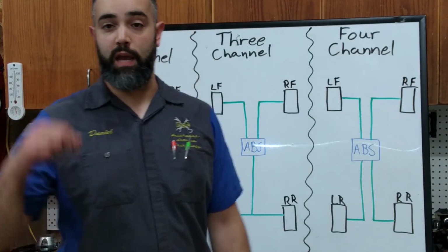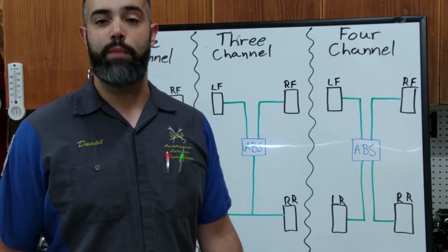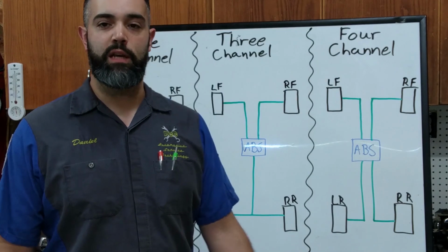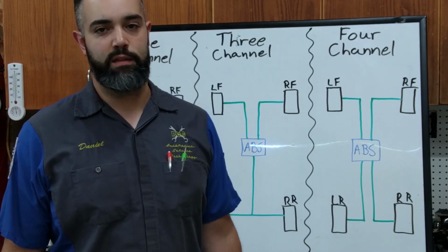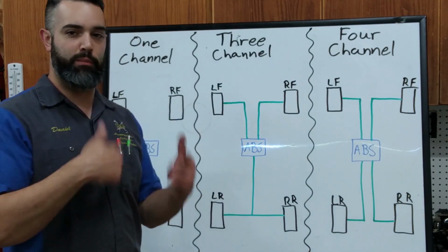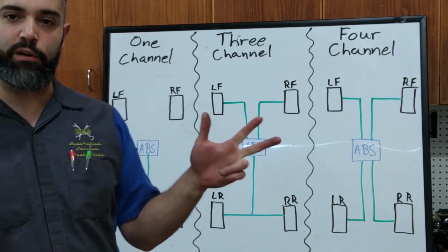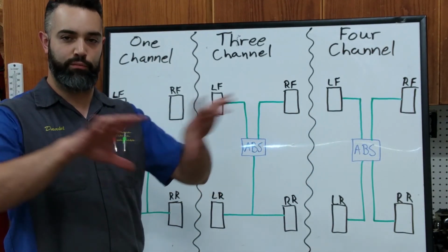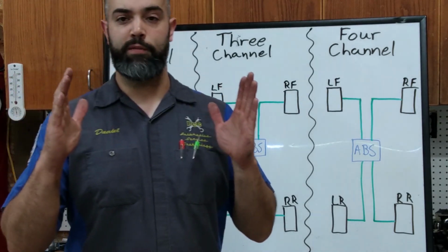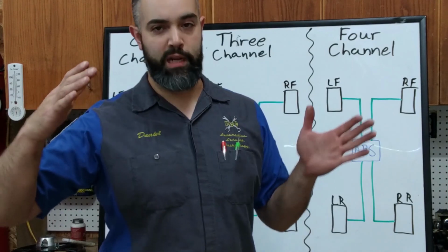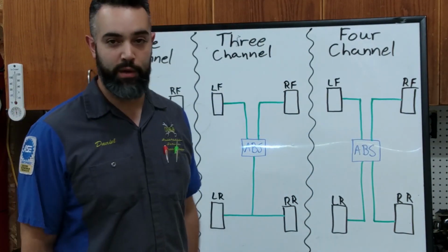So this would use a wheel speed sensor that is mounted in the rear differential, most likely, monitoring speed to both rear wheels. If either of those wheels locks up, it sends a signal and the computer can adjust and perform its isolate, reduce, reapply sequence to the rear axle, to the rear brakes together. And that will prevent the rear end of the vehicle from sliding sideways and potentially catching and rolling the vehicle, or going out of control and hitting something sideways.